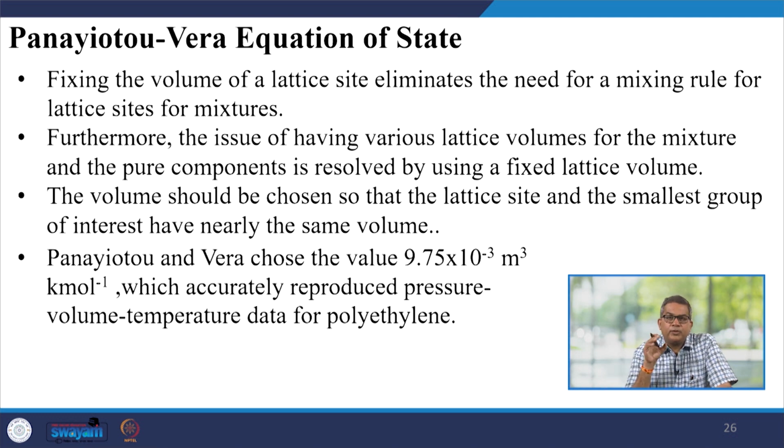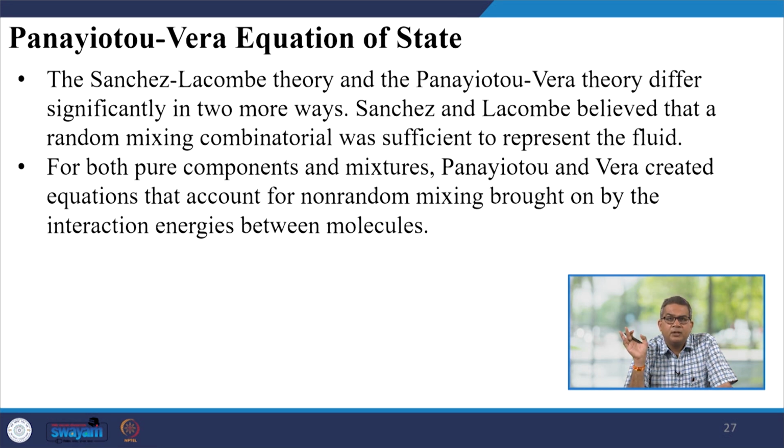The volume should be chosen so that the lattice site and the smaller group of interest have nearly the same volume. Now, Vera et al. chose the value of 9.75 × 10^-3 meter cube per kilomole, which accurately reproduces the pressure, volume, temperature data for polyethylene. So, all these things are case sensitive. Polyethylene, polypropylene, all these things are case sensitive.